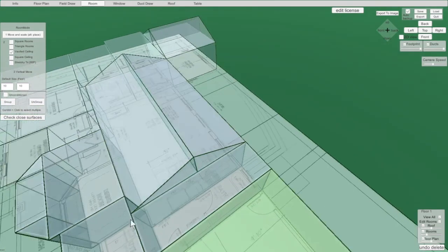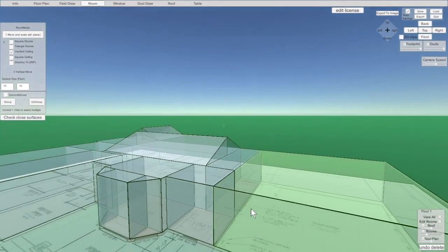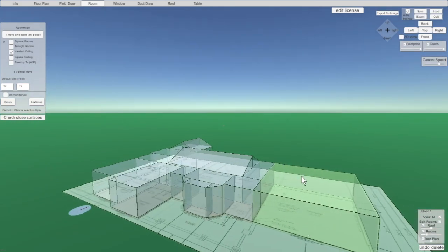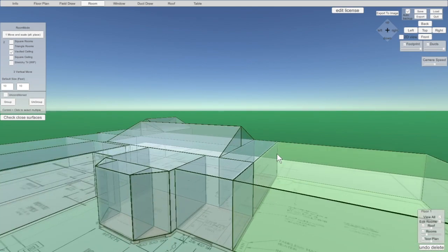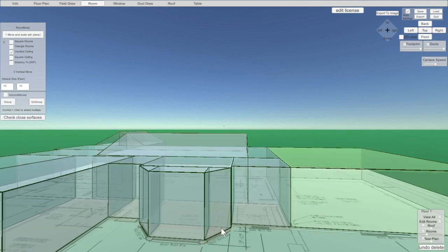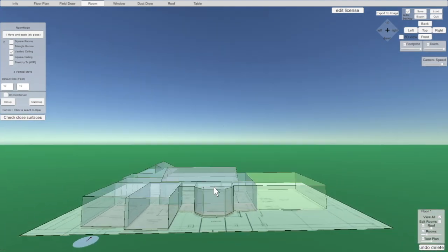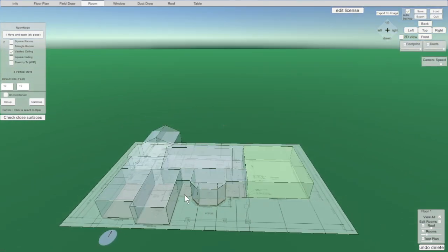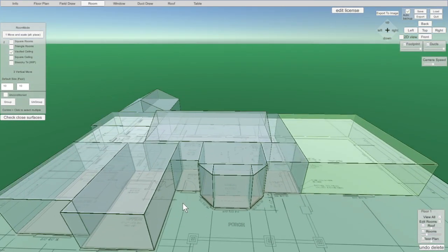And because the garage is unconditioned, it's going to ignore the garage essentially. It's not going to count any of these areas here, but it will count this wall here because that's between conditioned and unconditioned space. So there is heat transfer through these two walls into the utility room and into the bathroom and pantry. Okay, so it is counting those in the tables, and you'll see those in the tables if you go look at them. Okay, all right, next thing to do is windows.